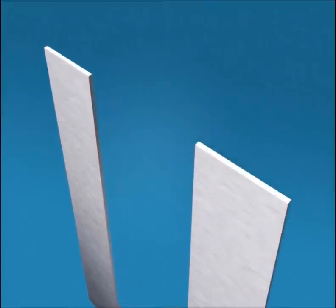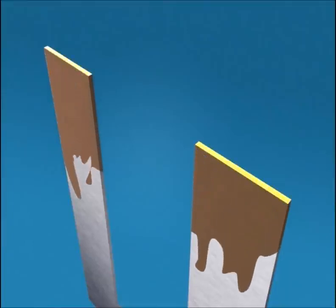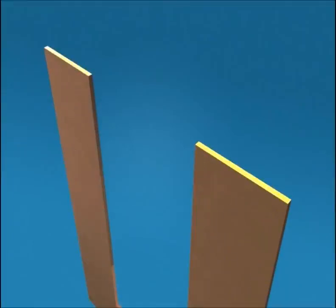The thickness of these laminations varies between 0.25 mm to 0.5 mm, and as steel is a conductor, laminations are electrically insulated from each other via a very thin coating of insulating varnish or by the use of an oxide layer on the surface.